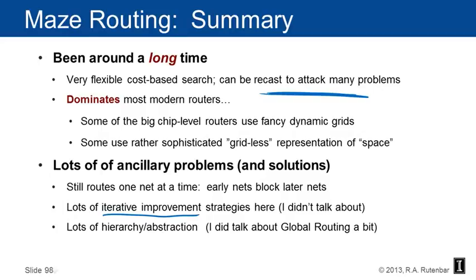And then you use the places where there are lots and lots of nets, too many nets, an unphysical amount of nets, and you use that to change the cost of the grid to make nets not want to use that space. You use basically a demand routing to create a demand map, and then you use that to put costs down, and then you can route things later. There are negotiation schemes where nets route each other and rip each other up. One of the things you can do is you can route a net, and in the consequence of routing it, you can decide to remove a piece of another net and ask the other net to reroute itself. There's very interesting stuff there.